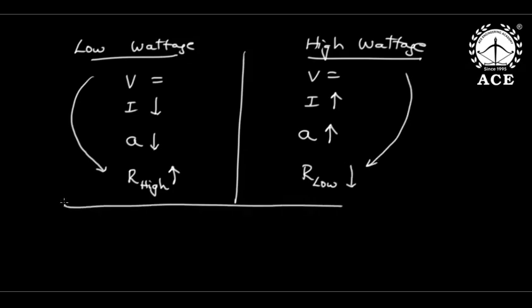So that is a simple thumb rule. In your house, if two bulbs are given, you measure the resistance. Whichever bulb has low resistance, that is high wattage. Suppose you give me two motors, I will take the armature resistance. If the armature resistance of any motor is less, that is high wattage.